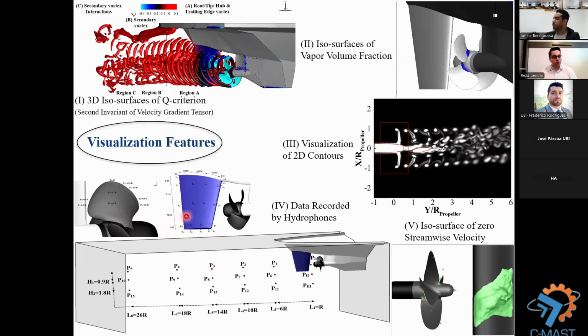In experimental work, for example, locating a microphone over the surface of a blade and rotating that blade is very difficult or impossible. But in numerical modeling, it makes analyzing the flow very easy. We located, for example, a microphone here, microphones over the surface of the blade in different regions, and also all over the computational domain. By recording all parameters of the flow, we analyze the noise generated by the propulsion system.